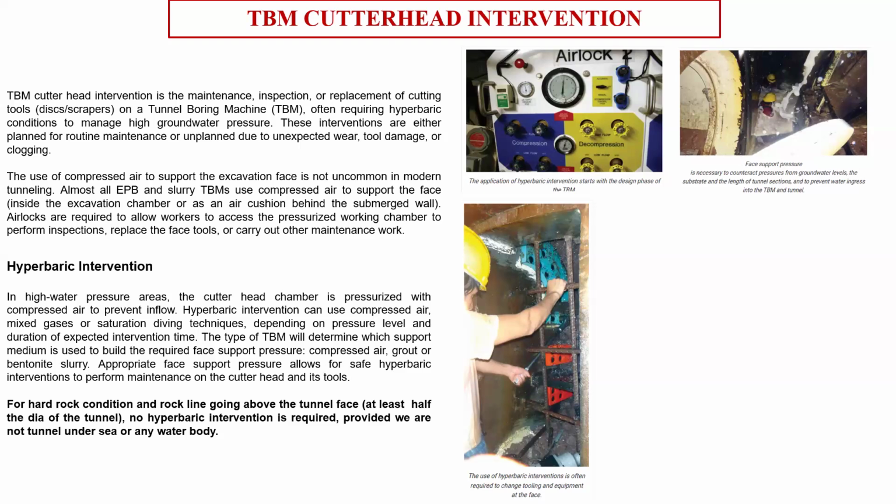But once the TBM segments have been installed, as per the survey, I need to check whether the segments have gone out of tolerance. Only that part I have to check. Sir, is it clear? Yes, sir. Because the curvature part in the operation, I cannot do anything about as a designer. But once the segments have been installed, in that particular curvature part, I need to see whether the segment circle has gone out of tolerance, because that is the main thing I need to check.